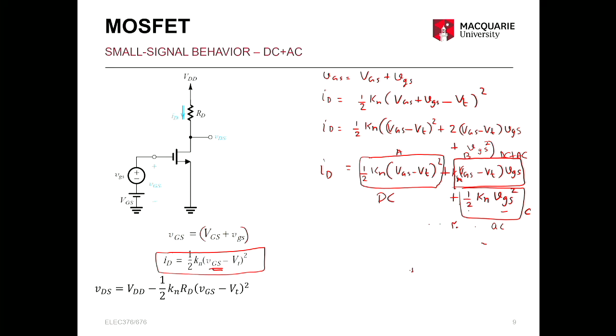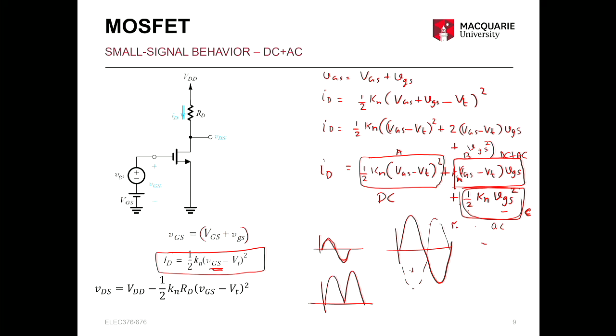Are you sure? I am sending a signal like this. What I want is an amplified signal like this, or with a phase shift the other way. Here what C gives me is the square of the sine wave, which will look like this, right? So that's not what we want. We want the accurate reproduction of the input, but in an amplified form. So B, that is where the amplification happens.